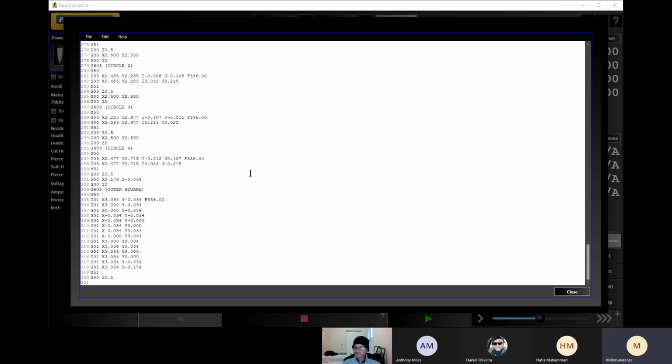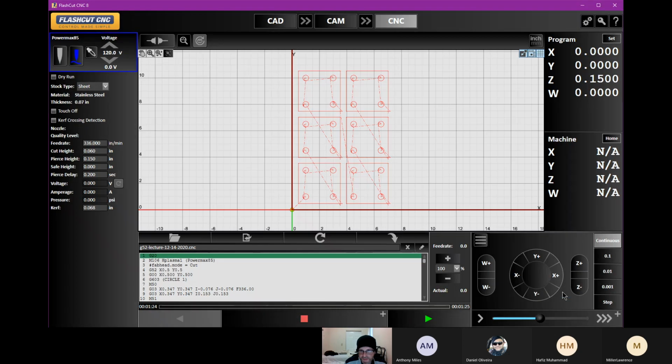So when it comes to duplicating parts, this is the method that most people are most comfortable with. Just G52. And you can put it anywhere you want, okay? Let's put one out in a random position somewhere, okay? Let's say we want to put one out here, okay? Let's go with X12 Y4. So our G52 will create a virtual 0 at X12 Y4.